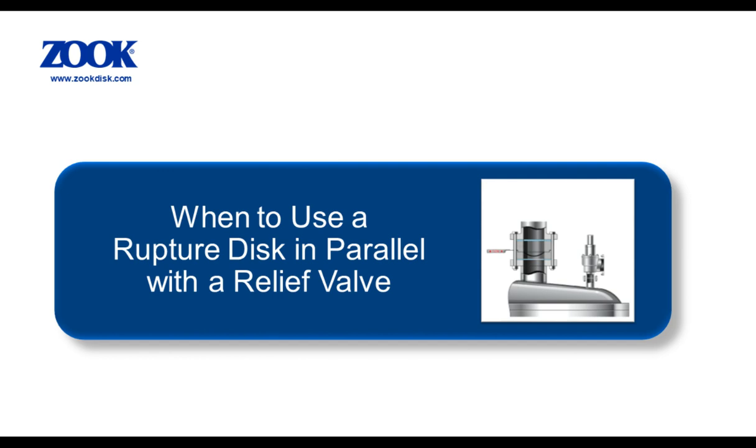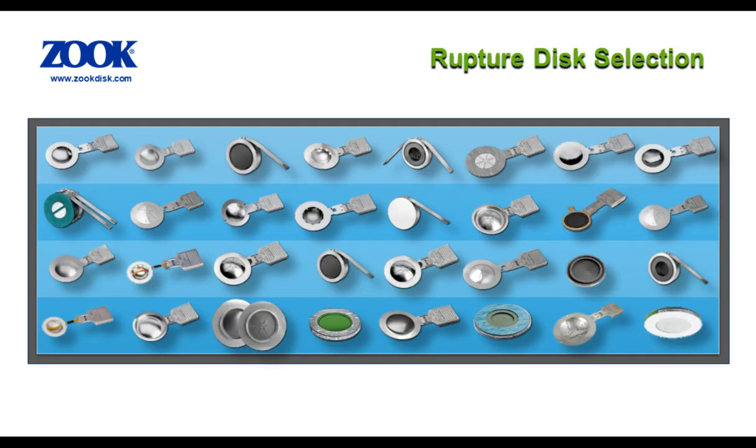Rupture discs could also be used in parallel with the relief valves. A relatively small relief valve can handle any low pressure relief requirements, with a rupture disc to provide additional capacity for extreme requirements, for example a fire case scenario. This saves the high cost of installing a large relief valve, which is not required for most relief cases.